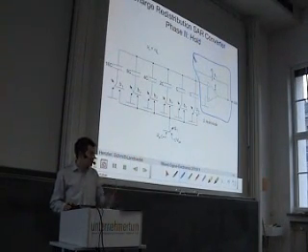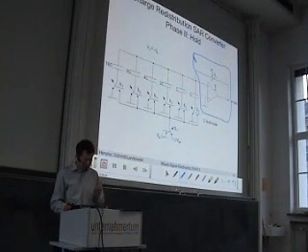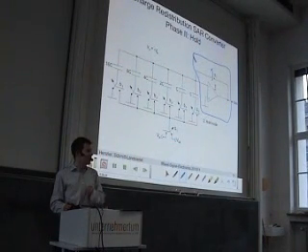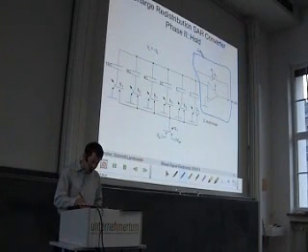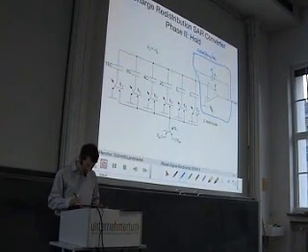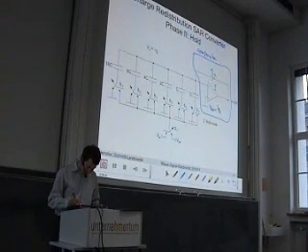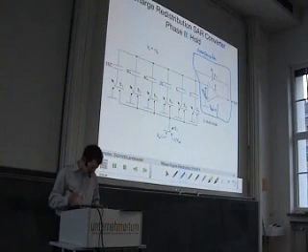There is no feedback. And what does it mean if there is no feedback? Yes, this op-amp does not work in linear mode of operation. However, this becomes now a comparator. And the output signal is V out, depending on the input differential voltage. So this is our input differential voltage Vd.